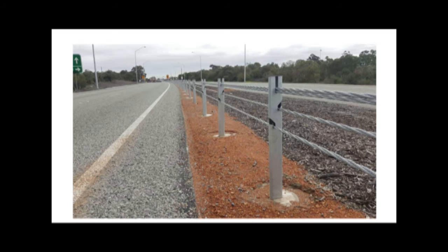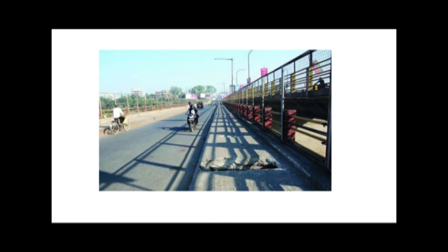While we provide the pavement or the macadamization of the bridge surface, the camber is maintained, ensured to be present so as to divert the water. So proper cavities or galleries are provided in the deck slab of the bridge so as to divert the water away from the surface of the bridge into the obstruction below, into the river channel or flood basin or whatever it is passing over. Then it is either taken in pipes or ducts, or it's directly taken down into the surface.